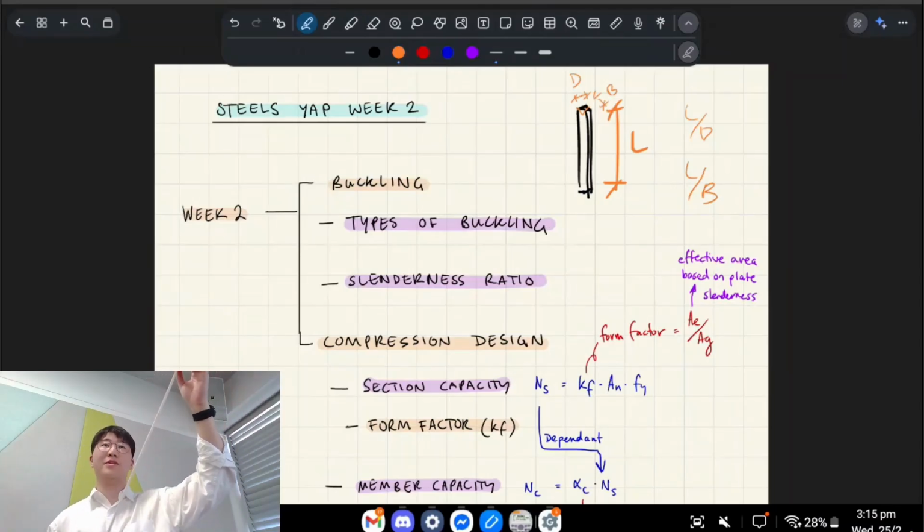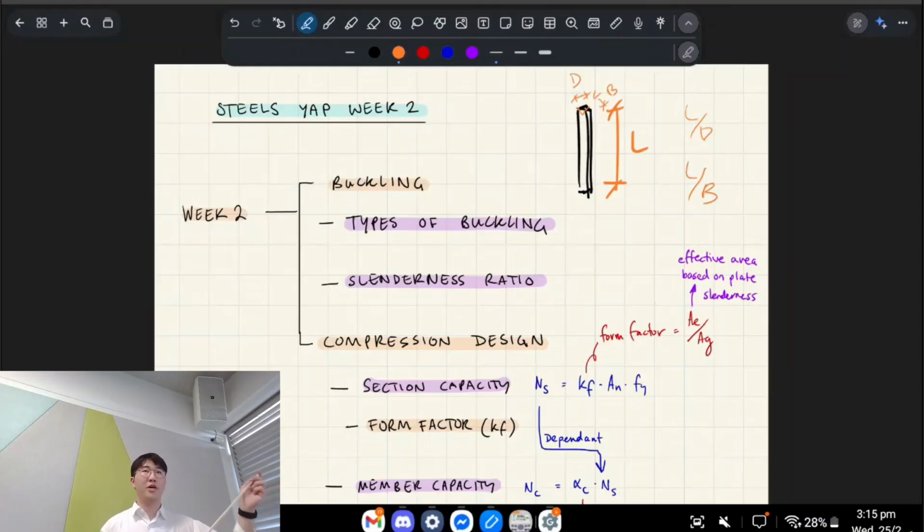Now buckling, I think I mentioned this last week, buckling is elastic, so I can undo it actually, but it's going to cause an early failure compared to what the material should theoretically be able to take in compression. You know what I'm saying? You can see that it's about to snap basically, right? Because it almost has this bending stress induced by buckling. Oh, nearly broke it. Okay.